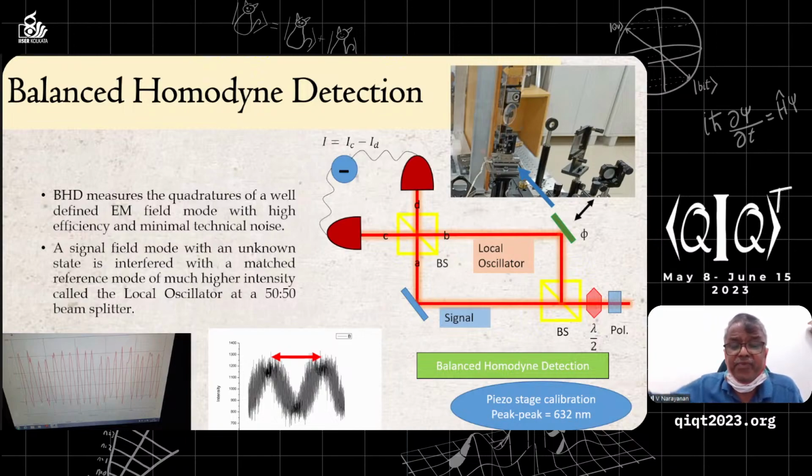So here, the challenging thing is to get the phase information corresponding to the current difference measurement, which is non-trivial. In order to do that, the phase measurements are done in a very precise way, because the wavelength, if you use any light, even from visible 350 nanometer to 600 nanometer, which is mostly the visible, and then you have IR, is very, very small. So doing a displacement or adding phase information is quite challenging. So one uses nowadays, which is readily available, something called the piezo stage, which moves in terms of nanometers.